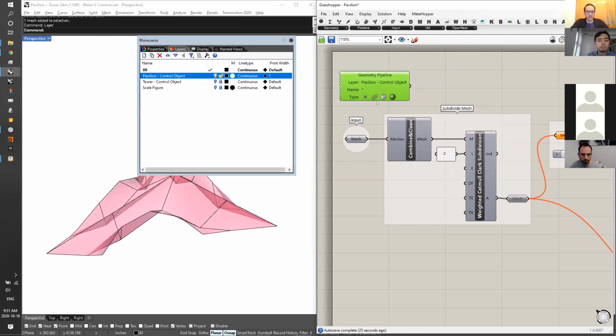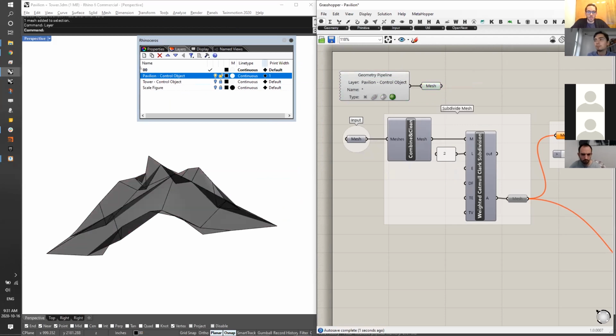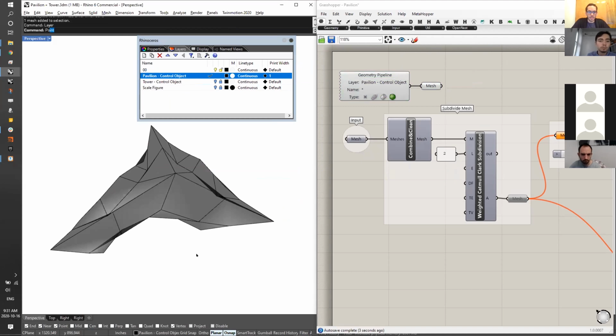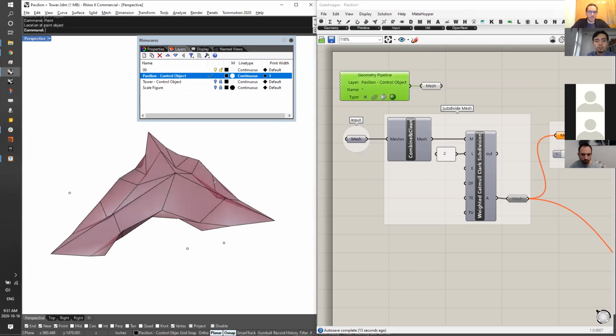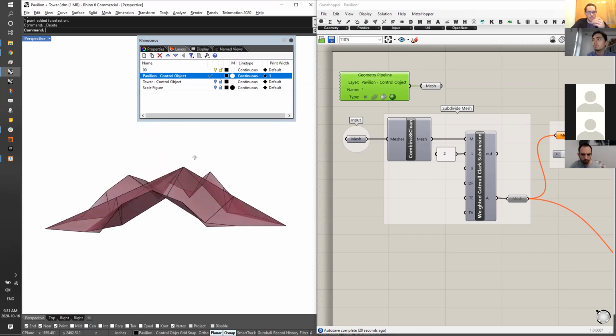So as you can see, it's automatically reading back from Rhino the contents of Rhino within that specific layer. And since I toggled on the mesh type filter, it's only returning back a specific filter. If I put a point in this layer, nothing really happens. It won't show up on here, unless of course I enable the points. And if I do, this is going to go red because I can't convert a point to a mesh. This is a fairly useful tool whenever you're doing any sort of live editing or just sketching out your Grasshopper definitions or solutions for a project that you're unaware of.